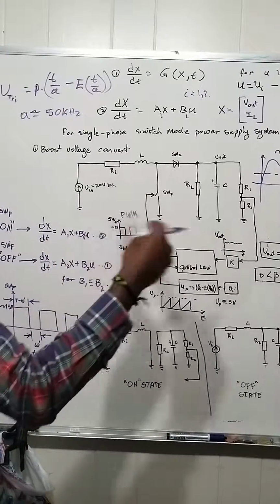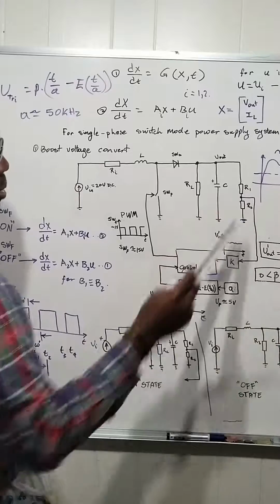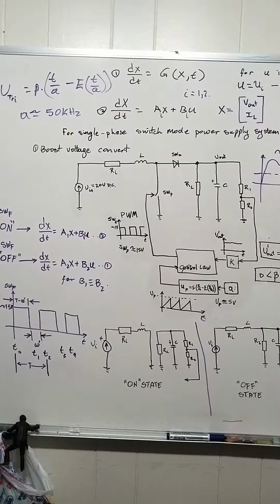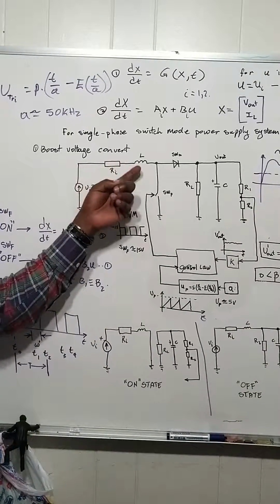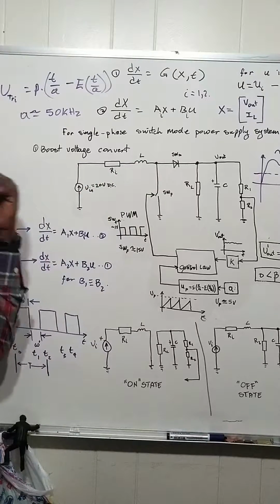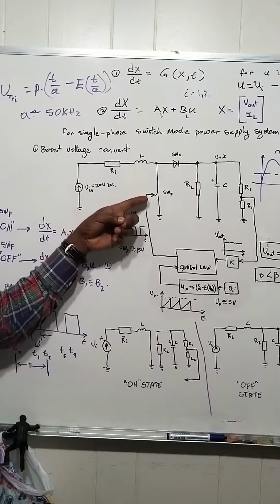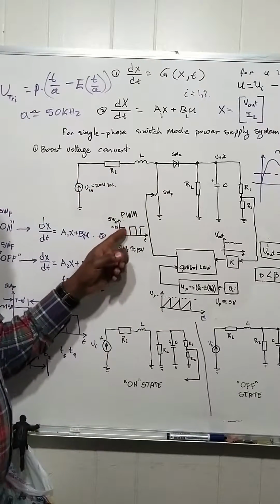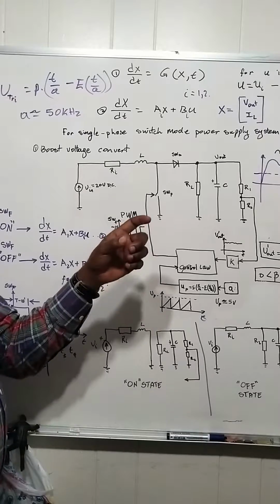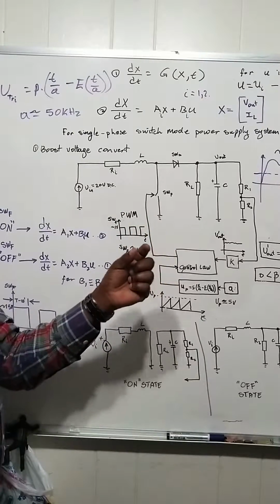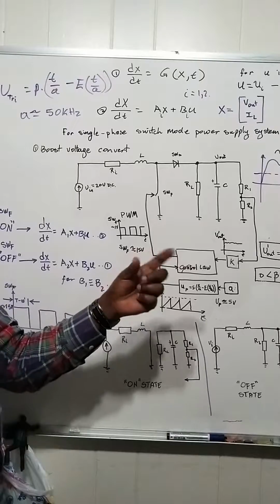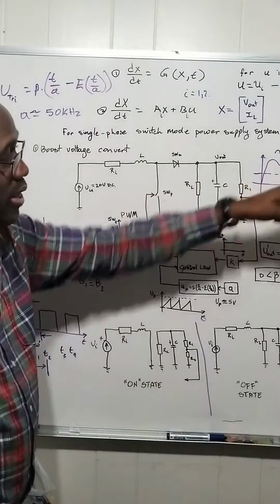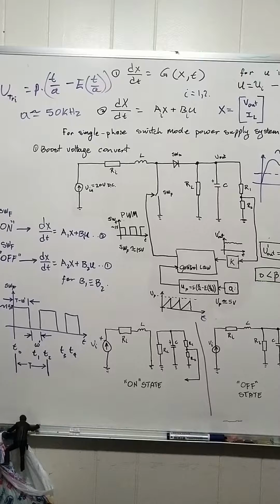And as it goes on, it steadies off. There is a bit of overshoot on the system, because as this generates energy in the initial stage, the switching needs to vary, either the pulse width is wide or narrow, until it stabilizes. Once it stabilizes, you get this nice smooth constant output, which is considered the steady state of the system.